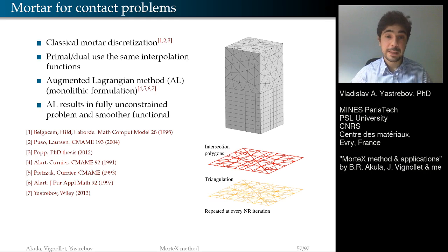And this accuracy is needed especially for the wear problems, in which the wear criteria often use either contact pressure or dissipated energy in the contact interface. If you have some kinks in the interface pressure, these kinks will be imprinted in the worn surface, and if the new surface is not smooth, it will create new kinks, and so the wear profile will be very noisy.